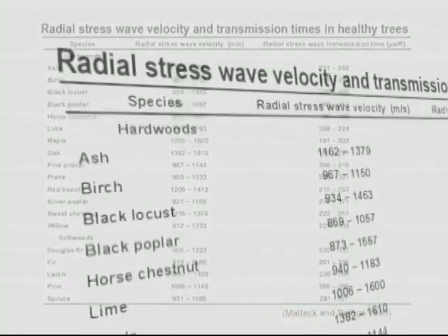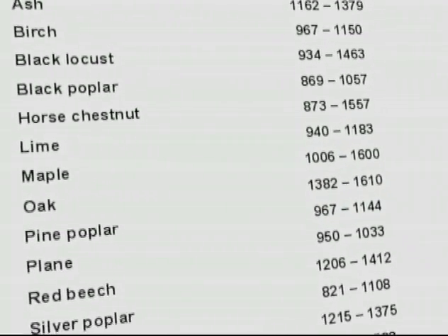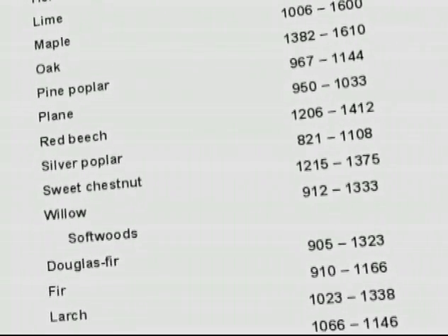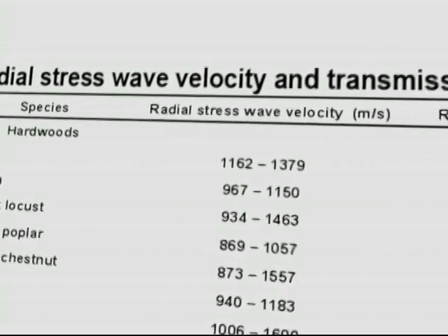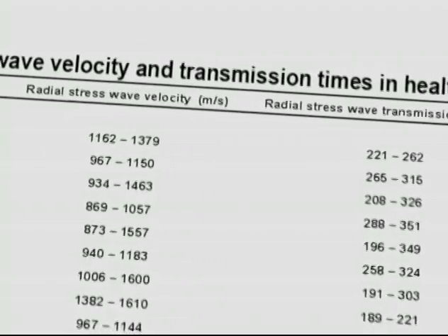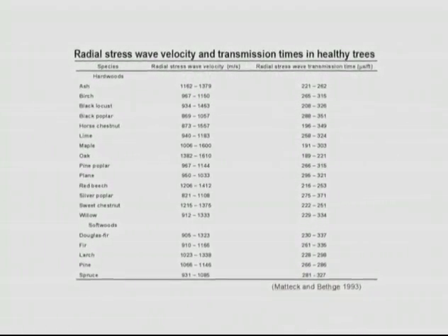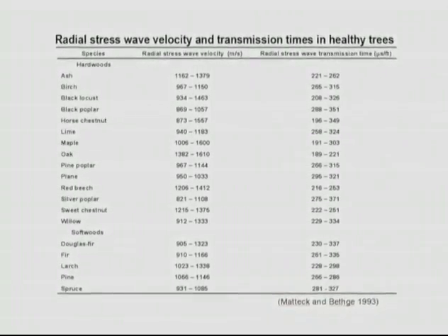Stress wave velocities of solid wood can vary due to moisture levels and tree growing conditions. Therefore, it is important to conduct a self-reference test on a part of the tree or a comparable neighboring tree that is known to be sound. In this study, if the sampled cross-trunk section had a velocity reduction greater than 25% of the solid wood reference standard, it failed the screening test.